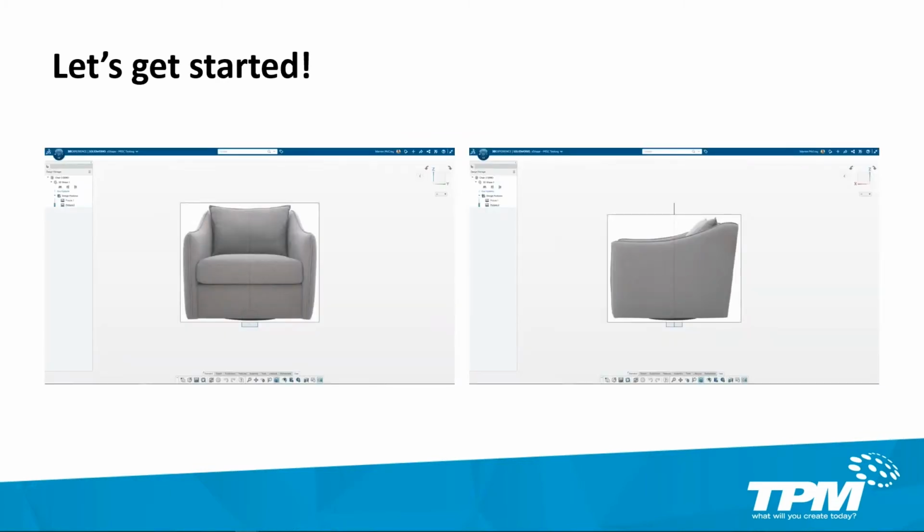I will begin the presentation within a single modeling environment where I have already added 2 photographs in an effort to save us some time. The front photo has been attached to the front reference plane, and the side photo has been attached to the side reference plane. I then scaled them to a desired size and lined them up as you see here. This process is very similar to adding a sketch picture within SOLIDWORKS. Now, if necessary, please adjust your volume on your PCs if required.